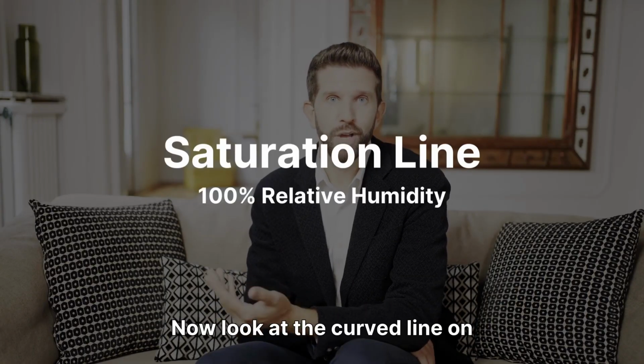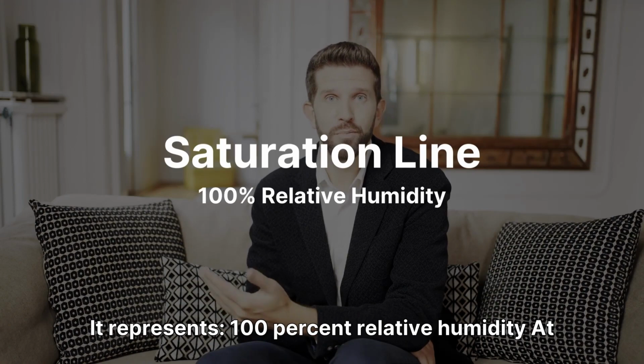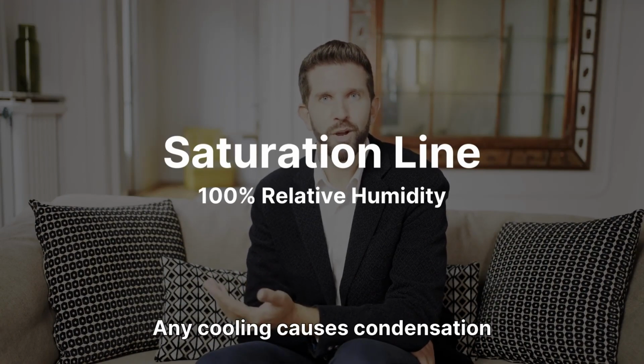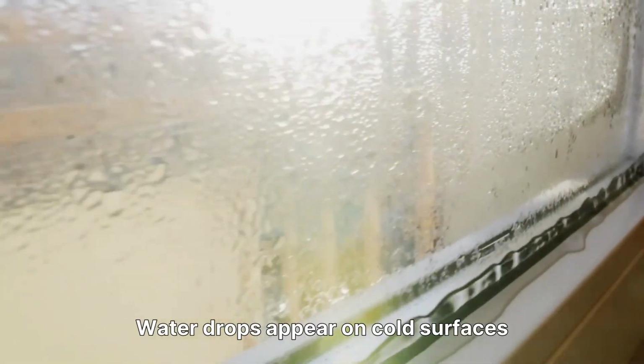Now look at the curved line on the left side. This is the saturation line. It represents 100% relative humidity. At this line, air cannot hold more moisture, and any cooling causes condensation. This is where dew forms, fog forms, and water drops appear on cold surfaces.